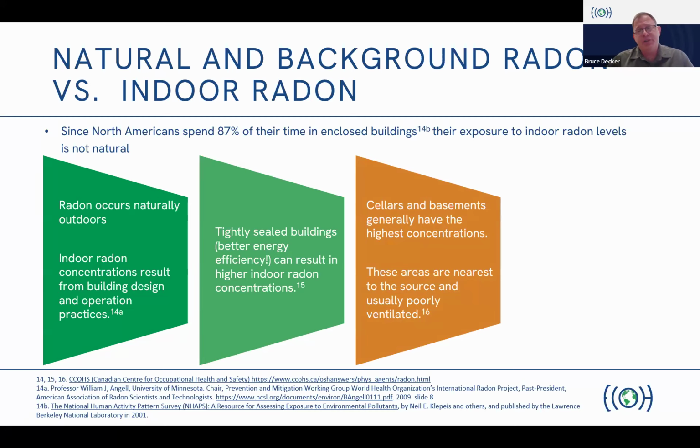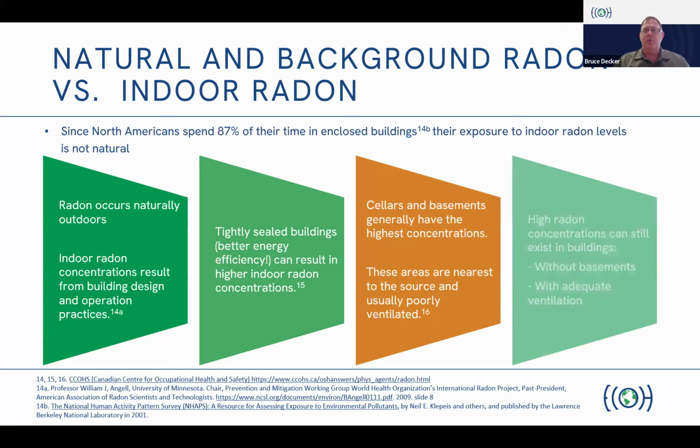A lot of people think, well, it's just the cellars, the basements that we need to worry about. Okay. And usually cellars and basements do test higher, but that's typically because they're closest to the source of the radon, and they tend to be less ventilated than the rest of the building. But that's not always the case. It's important to realize that high concentrations still exist in buildings without basements and in buildings with adequate ventilation. Okay. I have lots of case studies if you want to get into it. But in-ground ducting, that's the worst, right? That can be a big concern. Okay.